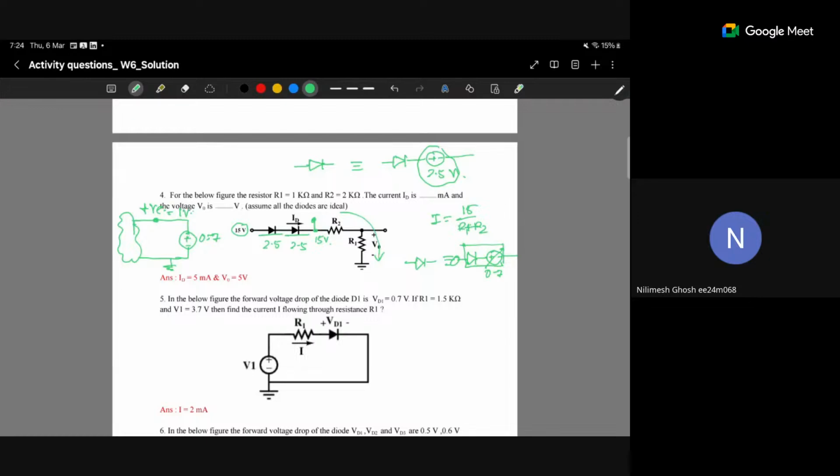Now the second case, if the diode is reverse biased, that is your reverse bias. Now no current will pass through here, right? So we simply open circuit this path, and whatever voltage was there previously, this 1 volt, now also there will be 1 volt across this region.